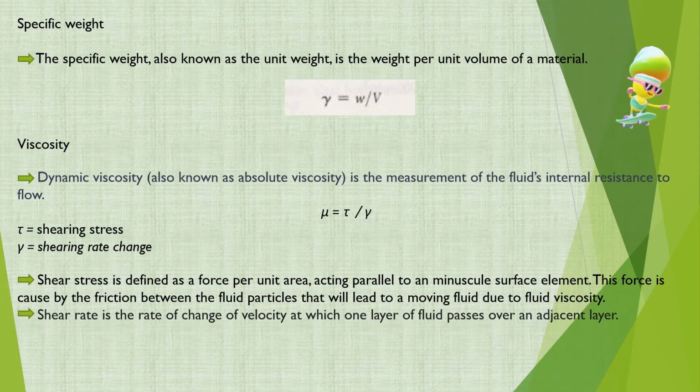This force is caused by the friction between the fluid particles that will lead to a moving fluid due to fluid viscosity. I give you one simple example. Imagine there is a container of a fluid. If we apply force to the fluid, it will be moving. Why? A fluid that is in a rest state cannot resist shear stress. That's why a fluid at rest will move if we apply force to it.